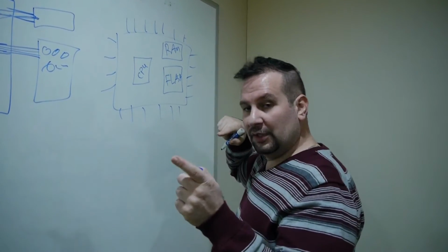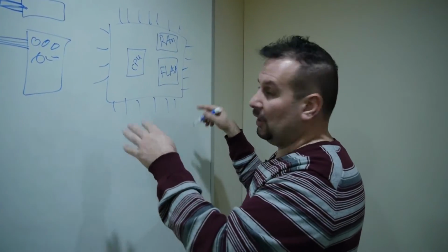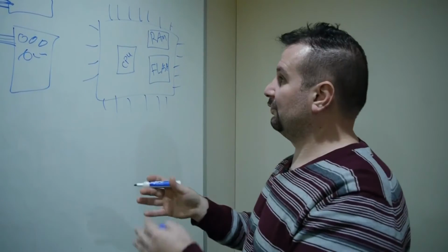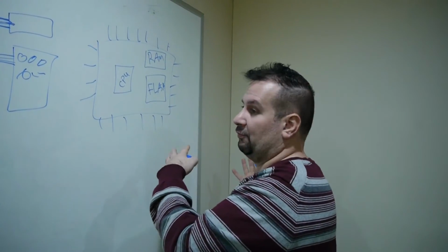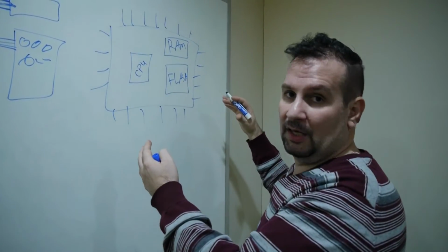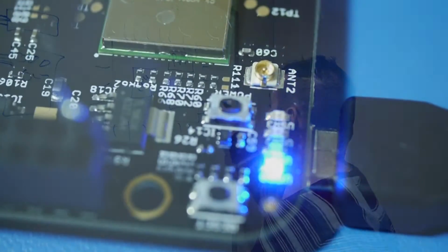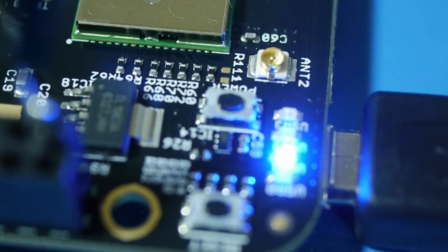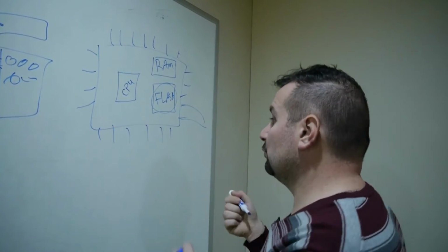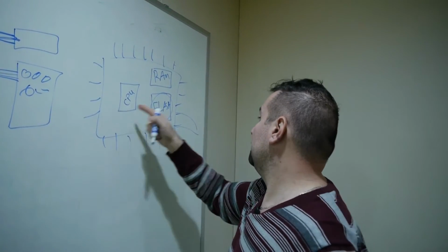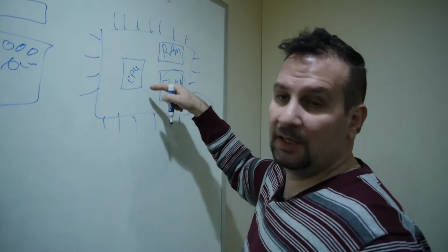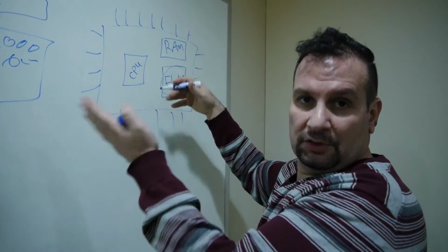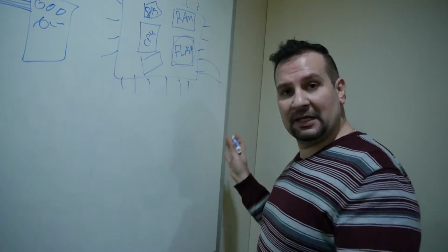Now, what we do here is after we are done, or let's say we are a microwave manufacturer, once we are done, we connect the circuit to a flasher or a programmer device that loads our software somehow onto the flash memory. Now, the next round, when we power up the system, the CPU will start looking at flash, just like the PC looks at the hard drive, and boots up. And then it uses RAM to function. So this is it, basically, what we do here.